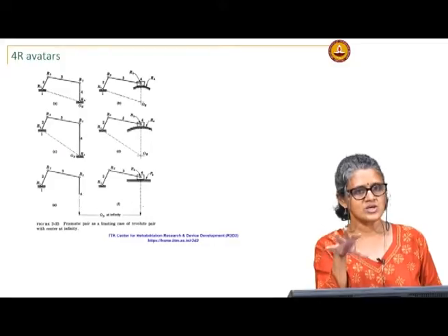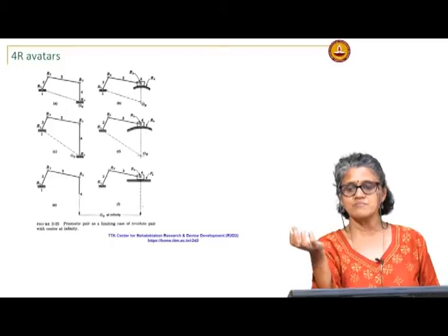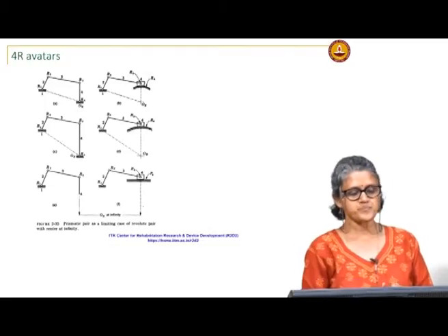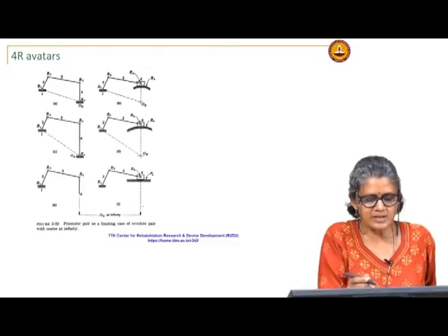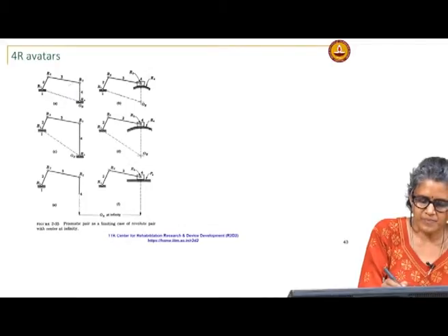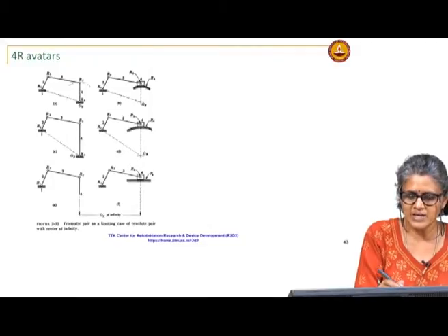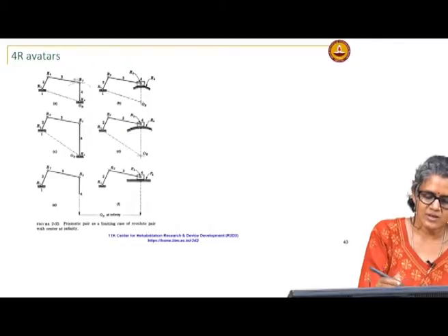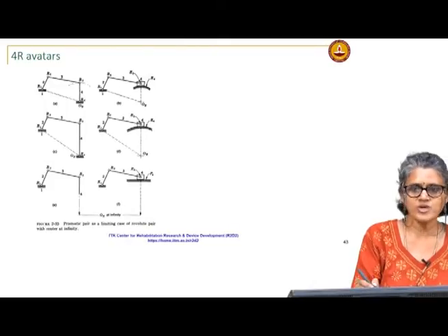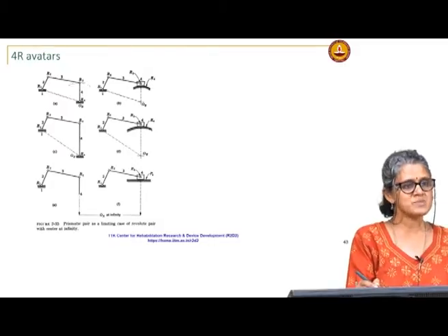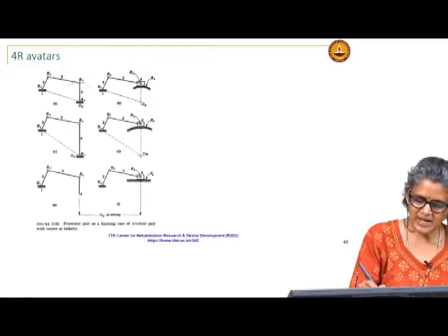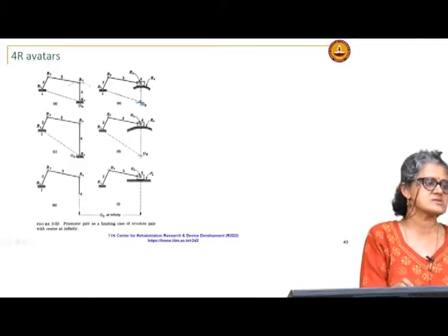Okay. So, in many cases you can make a kinematic representation of a link, say with higher pairs or with other kinds of joints, as a 4 bar for analysis. For instance, if you take this 4 bar, essentially if you look at the motion of this point, this link 4 is pivoted to the ground at R4. So, this traces an arc. Okay. So, this may be represented as a block with that curvature moving on that curved surface, but this is not really considered a prismatic pair, because it has a finite radius of curvature. So, this is actually equivalent to this 4 bar.